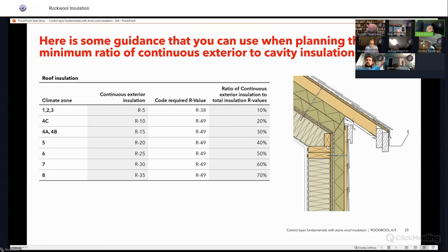because we may not have enough interior drying potential to really keep that system dry and durable over the long haul. Now that goes the same for your roof assemblies as well. So a roof is a wall is a roof. So if we have our ratios correct between interior insulation and exterior insulation, we're going to take our condensation point and put it out here in the insulation, giving it a path to dry right out of the assembly and keep that system durable.